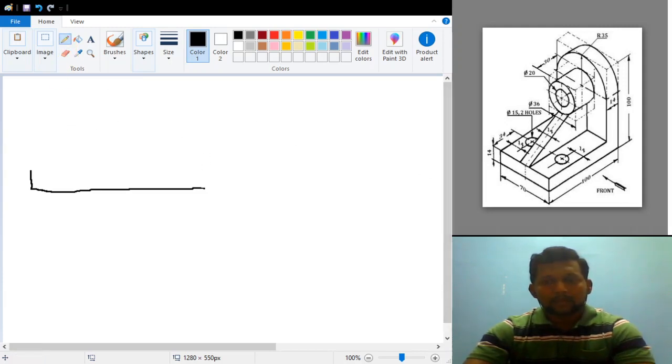After this we have this length, how much? This length is equal to 86. How am I able to tell this? Since this entire length is 100 and this block thickness is 14 mm, the left out distance is 86. So until 86, I'll draw this one like this.